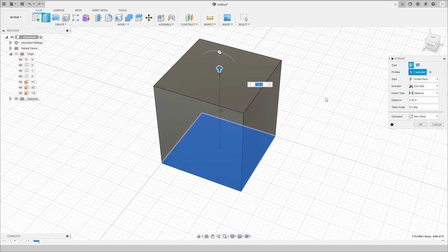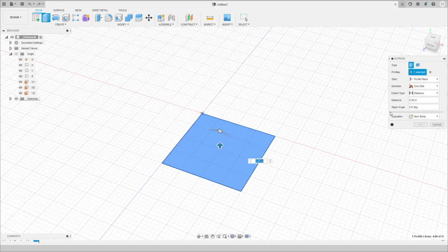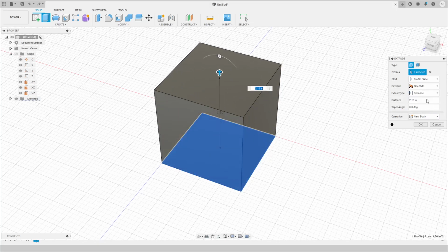The one-side extrusion is probably going to be the one we end up using the most, and it's pretty useful. In this specific type of extrusion, we're specifying the distance, but we might not always specify the distance. We might also want to extrude to another object, but that will primarily be in cases where there are other objects to extrude to. For now, these are the things that are important: the place it's starting from, the place it's going to, and the number of directions it's going in. The maximum is 2, both sides, and the minimum is 1, that you can extrude from a single sketch, because it exists in a 2D plane. That makes sense if you're creating 3D objects.